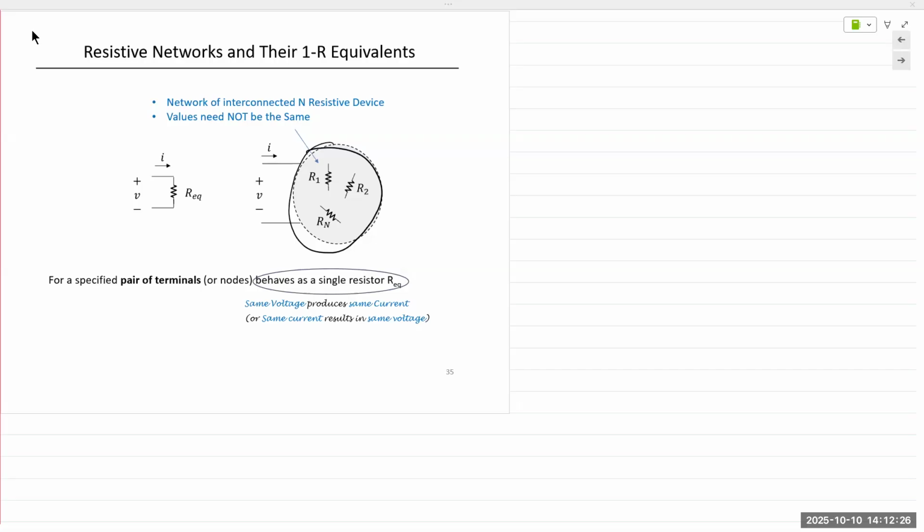Depending on how we connect it, as we saw in the previous lecture, we can apply Ohm's law and solve for that circuit. It does not matter how many more resistors we connect, the source is only seeing one single resistance. So when we perform theoretical analysis, we have developed methods where we can reduce that resistive network down to one single resistance. Two of them you're familiar with, connecting resistors in series and in parallel. There's one more that we'll look at today. And then we'll also look at the derivations for the series and parallel.